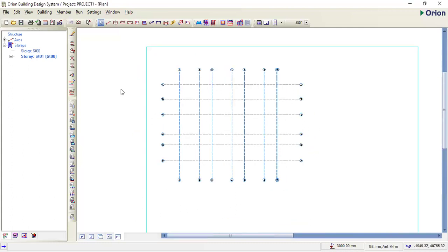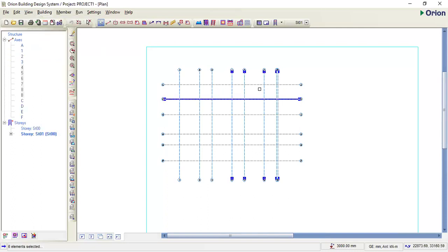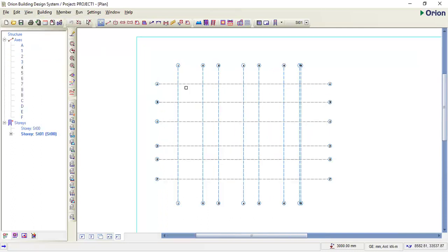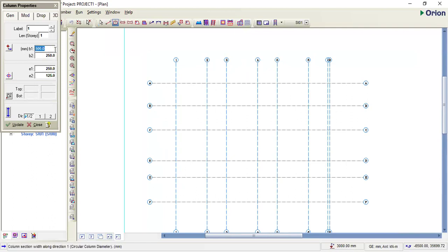If you also want to do further setting, go back to your building. You can see your setting. This building is particularly two suspended floors, that is 3 floors. Go to your column now. In this column, we have 230 by 230 all through. Then go to the center of the column, choose this icon and drop. You can go either way you want.